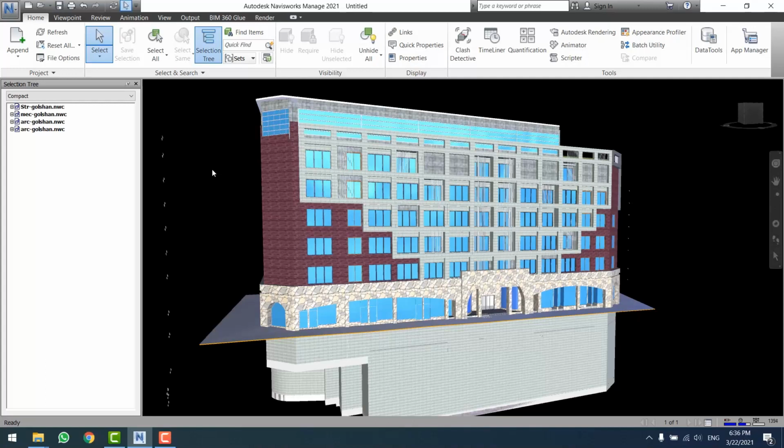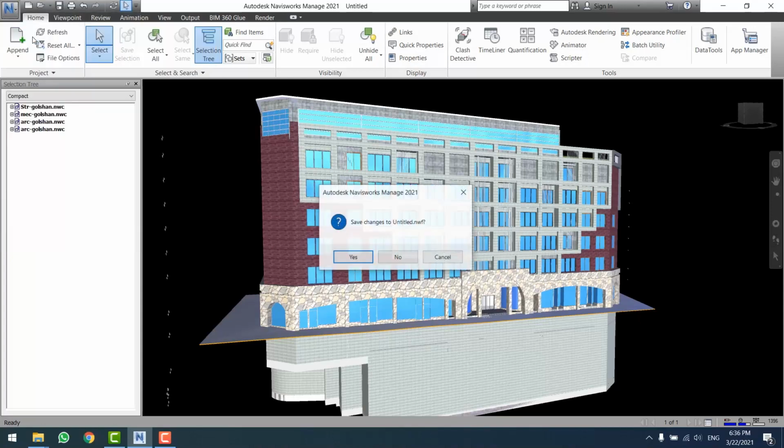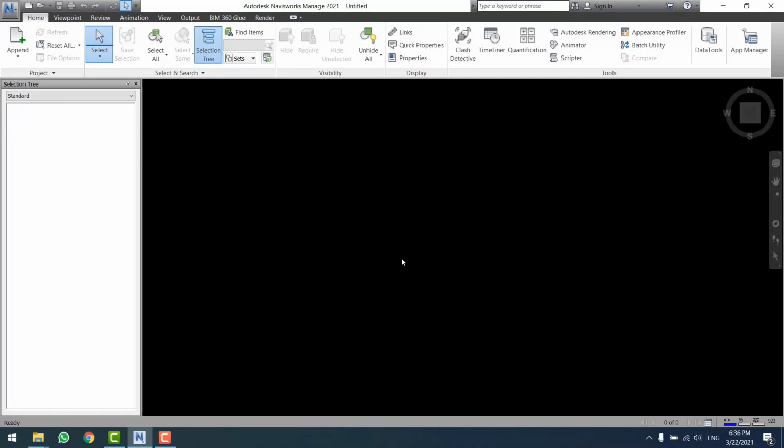You may want to close the view to just empty the scene, similarly to Revit or other software. In Revit, you're able to empty the page, and after that the trademark appears, but you cannot find such an option in Navis. But how can we empty the scene in Navis? To do this, we should open a new template file. So I click on No, then I open a new template file. As a result, we cannot close the project. Check this out, there is no close icon.